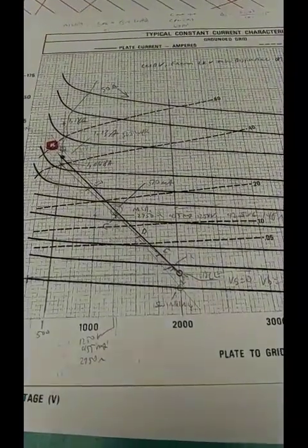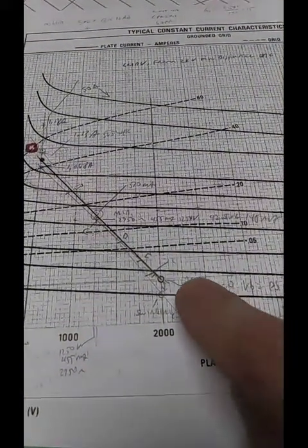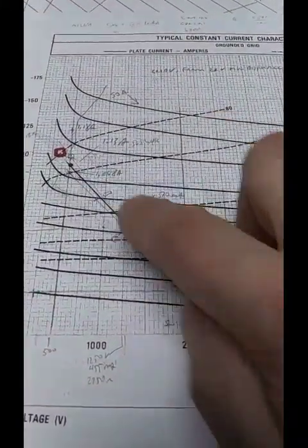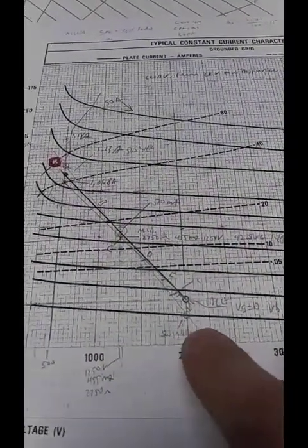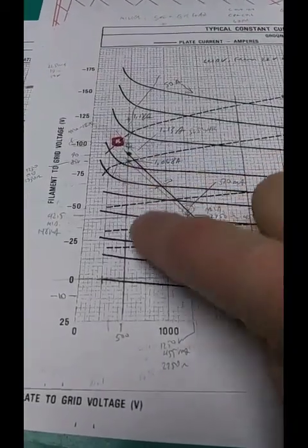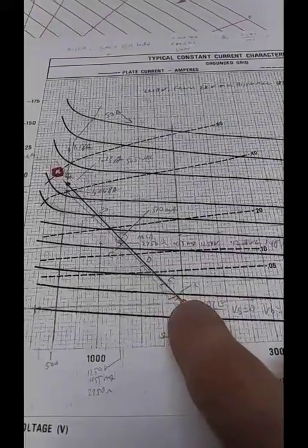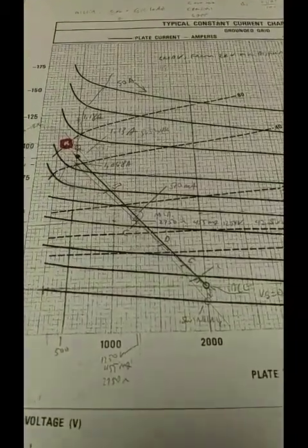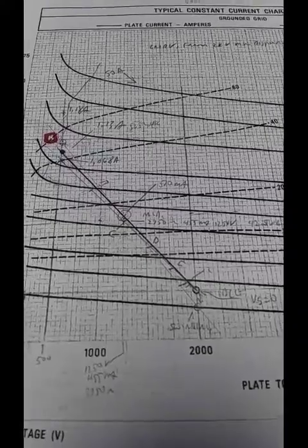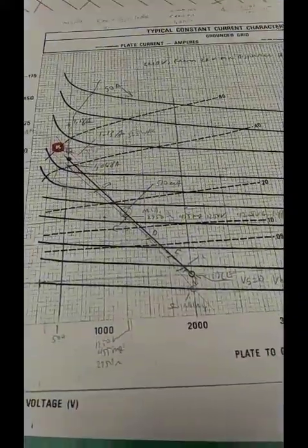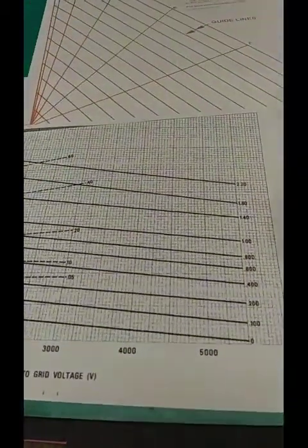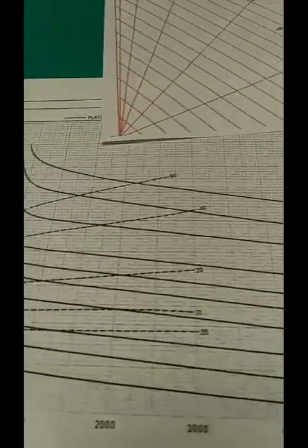What's meant by a load line is, for example, the solid dark line starting at the 2 kV plate intercept and going up to the left. This straight line is the so-called load line. That represents a particular set of operating conditions. 2 kV maximum plate, some minimum plate voltage, which is 500 volts, and that represents, in different parts of the operating cycle, different currents. Different plate currents over here, and different grid currents there, and there's no screen, so no screen current. There can be a very large number of lines that can be drawn. There are three of them there in my process of trying to figure out the correct one. From geometry, a line requires 2 points to be defined, but they must be the correct ones to satisfy that on here.